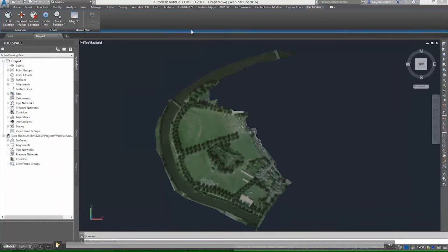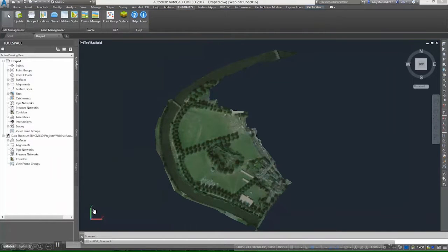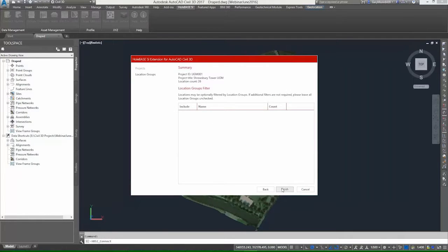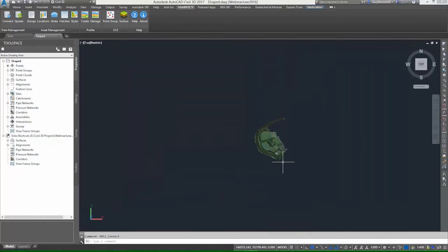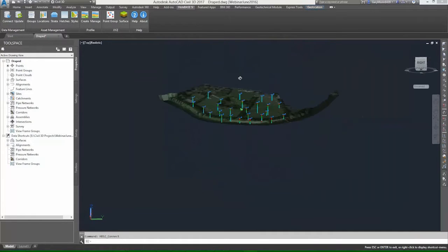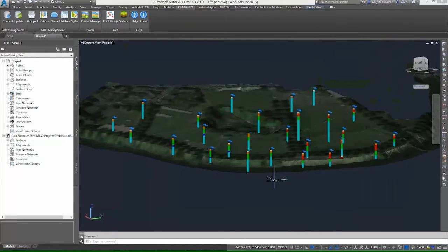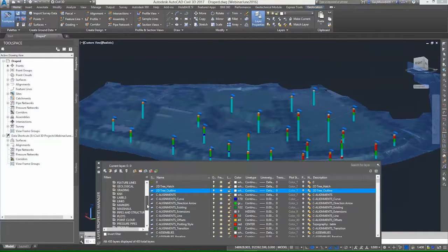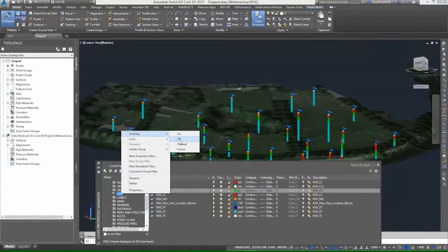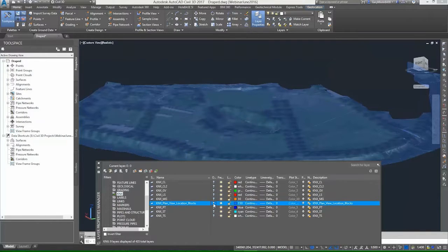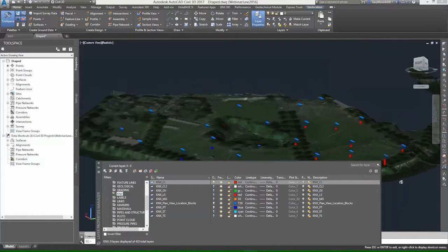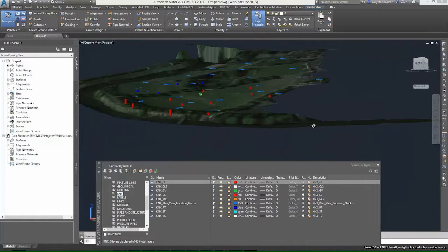In a similar scenario, we've got this right here. If we can pull the data quickly into AutoCAD Civil, then we can start using it to visualize and wonder what's going on around the site. So here I've got a ground survey and I've draped an aerial image over the top of it. But look now across my site, I can very quickly see where I have different geologies. As we pull the data in, we've put it onto different layers. So for instance here, I can turn off all of my different types of geology across the site, and now just start turning on where we found different styles of geology as we did the drilling of the holes. So we have some peat in one area, we have the red clay in another area. Can you see how quick and easy it is to see this geology in context of the actual site?